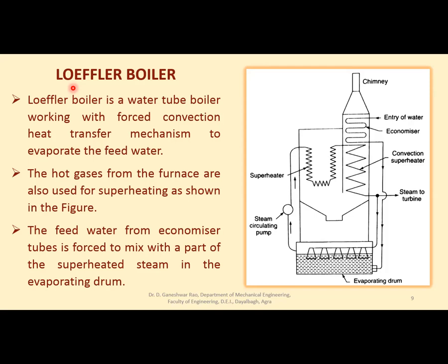It has another disadvantage: that deposition increases the danger of overheating of the tubes, due to salt deposition, which has high thermal resistance. That difficulty was solved by the scientist Loeffler by introducing a boiler in his name, the Loeffler boiler. In this, mainly the flow of water into the boiler tubes is prevented, right?